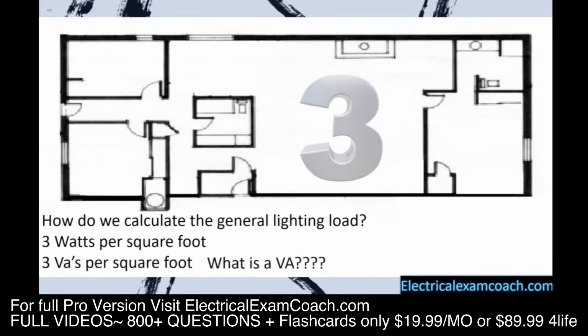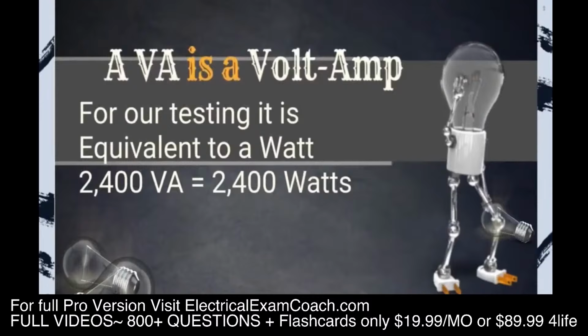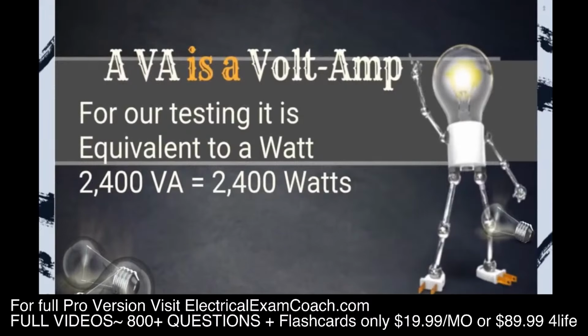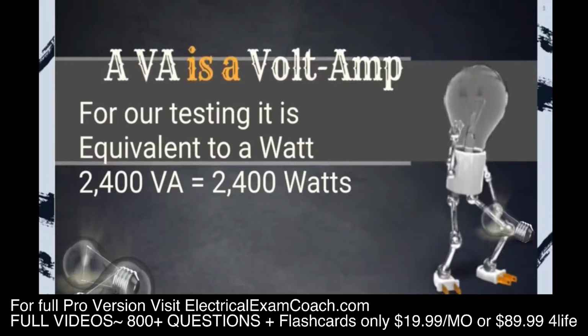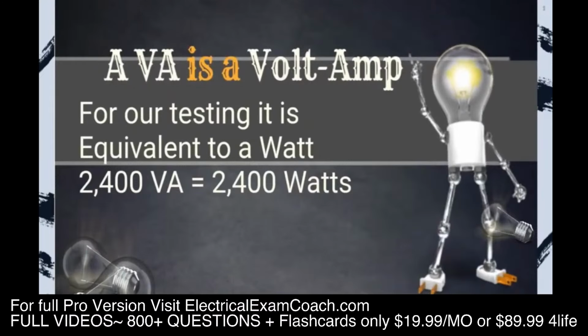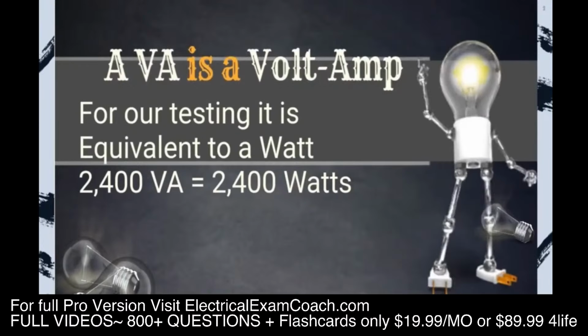But the question is, what is a VA? A VA is a volt amp, and for all of our testing, it's equivalent to a watt. So it's true for us to say that 2400 VAs is equivalent to 2400 watts. So for these calculations, we're going to be calculating them at 3 VAs per square foot.